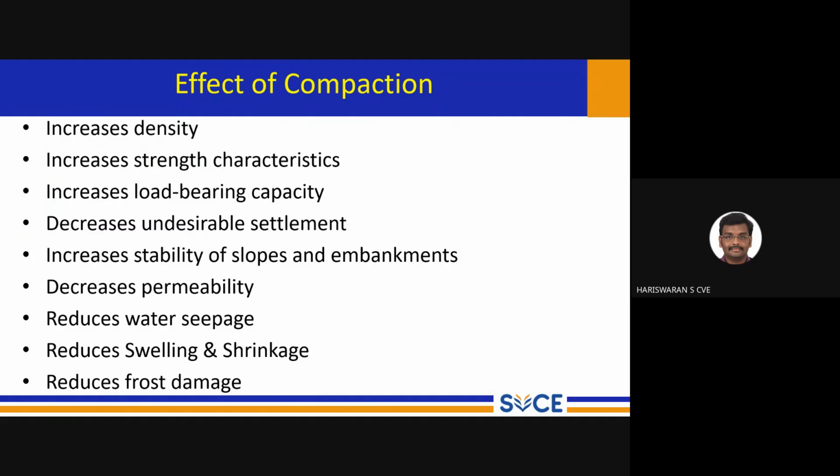But there is another criterion: in which case is the volume of voids higher? Everybody has a myth that gravel has more volume of voids. Actually, not. Gravel has very large voids, but the number of such voids is fewer.